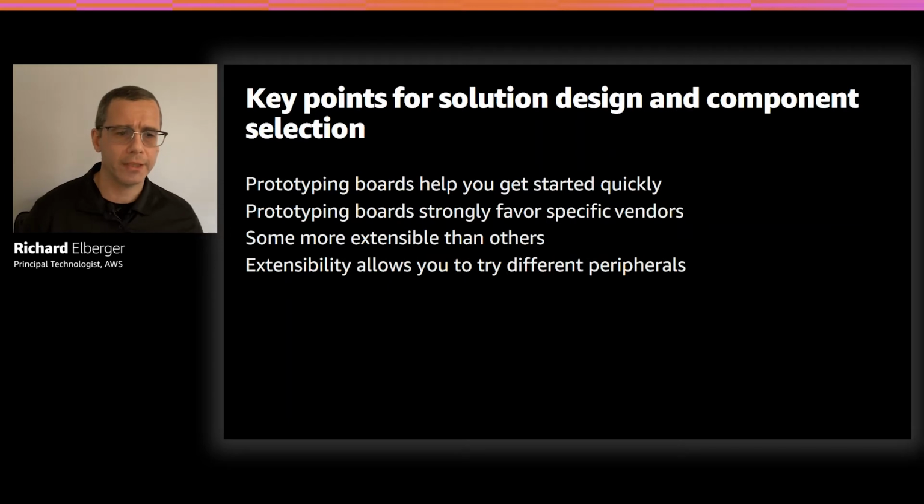What we saw in this section was an overview of component selection. What you can keep in mind here is that there are development boards that align with your use case. Don't do it the reverse way. Don't get a development board with a connectivity module that you feel married to. Do the analysis about the right module for the right job. I've seen many times where people felt married to a specific communications module and type and didn't do a deep evaluation of the right module for the job.